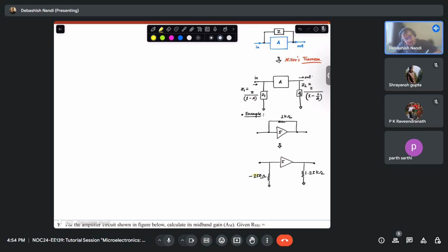So what is your comment on that? You are realizing a negative resistance. Power gain is there. Basically, it is the input resistance. And believe me, this happens in amplifiers, and this is just a fun fact for you guys. This causes stability issues.